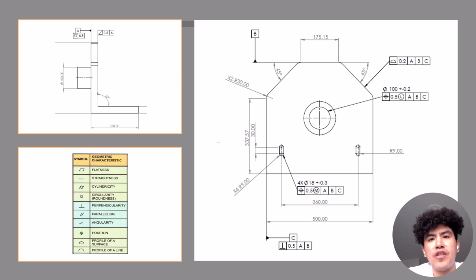This project applies GD&T principles to an electric motor mounting plate, verifying the position of the keyholes under maximum material condition (MMC) and least material condition (LMC). The proper use of GD&T improves interchangeability, reduces manufacturing errors, and also reduces cost, because companies don't need to fabricate extra devices until they get the real one.